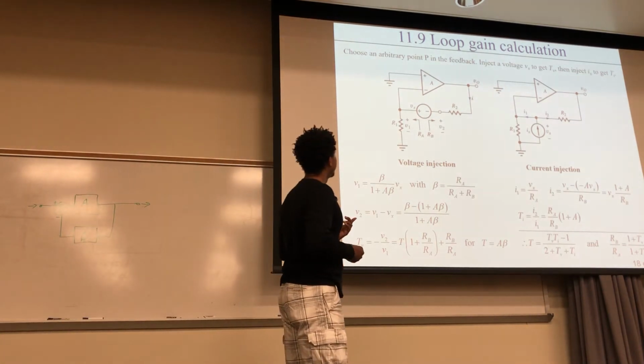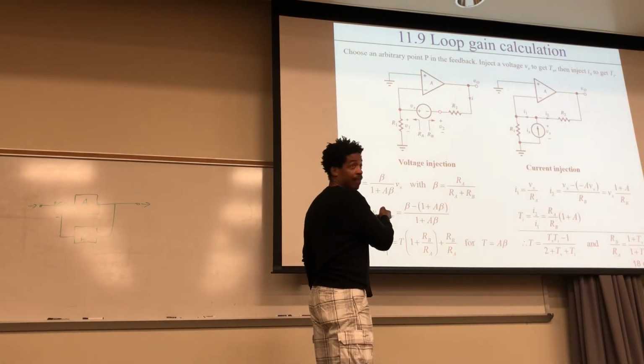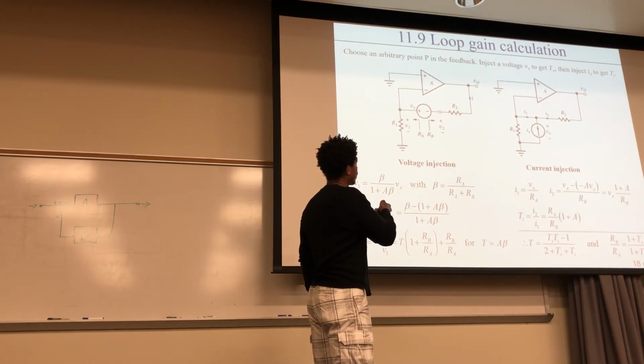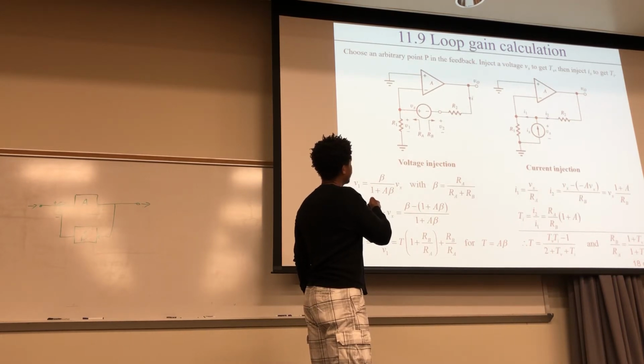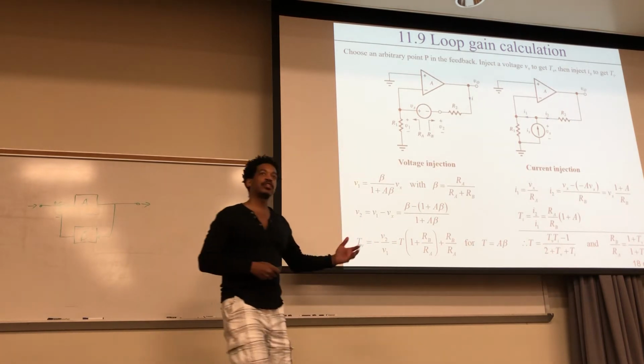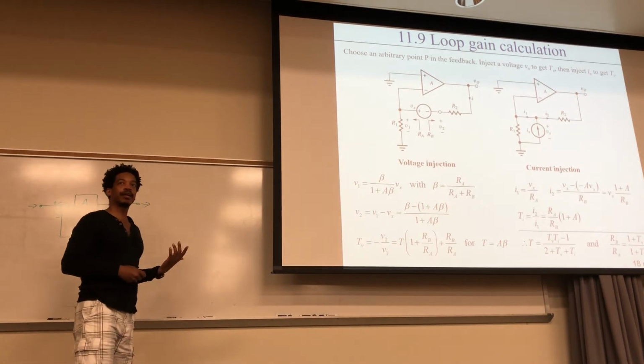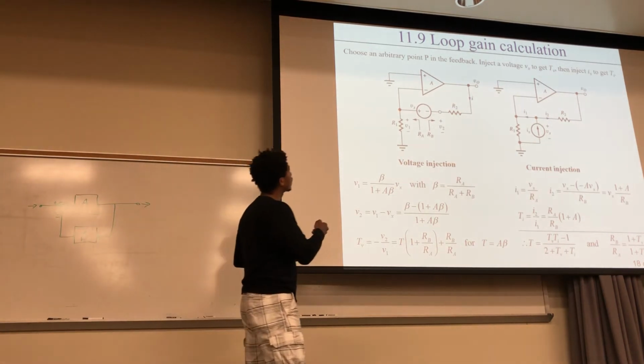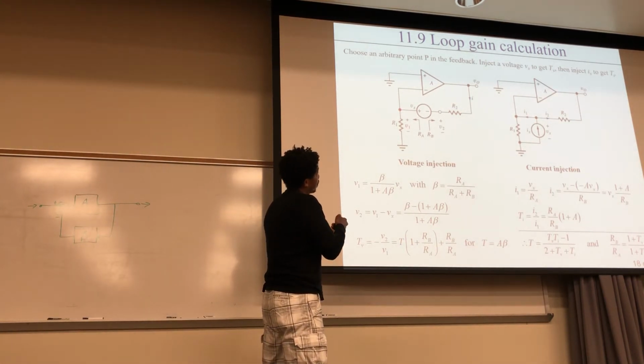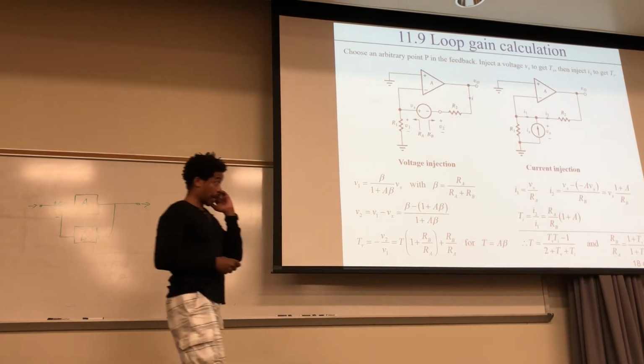Yeah, if this was grounded, it would be equal. But that's V2. V2 is, with respect to ground, the voltage right here, right? So if I go through here, the voltage right here is going to be V2 plus Vx. You guys see that? So you could say V1 equals V2 plus Vx, but this thing here is a change in voltage of Vx going that direction. Okay.